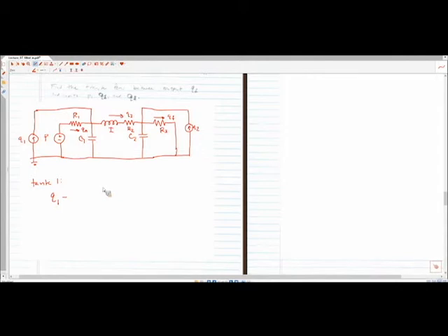We also have coming in P minus P1. So make sure we label this node P1, P2. This is divided by R1. We have then Q3 coming out. We'll get into what Q3 is in a second. This is a fairly complicated expression, so we'll just leave it as Q3 for the time being. And then we have the fluid flowing into the accumulator or the tank, and we'll take a look at what that is in a second.